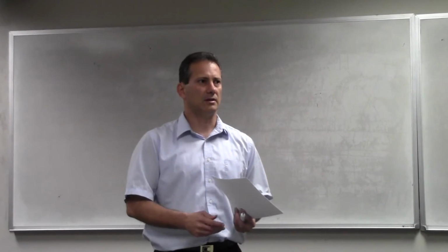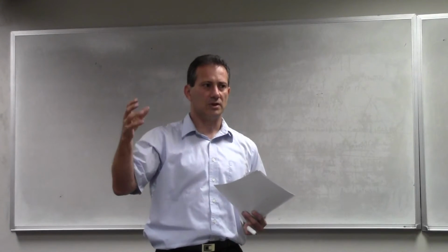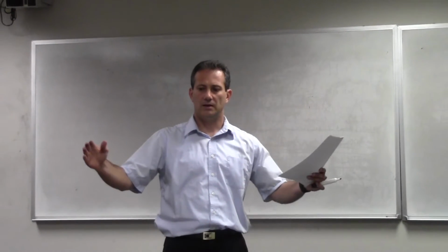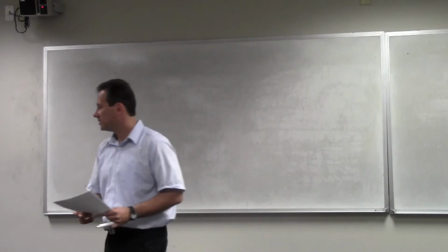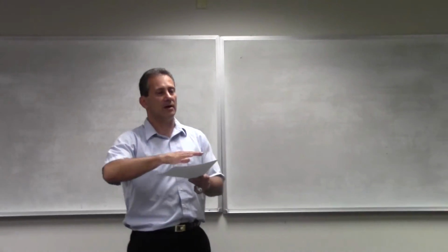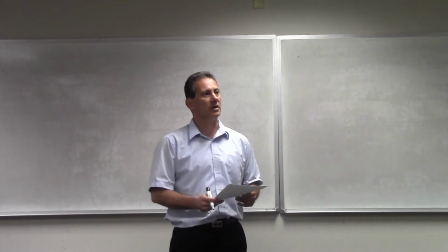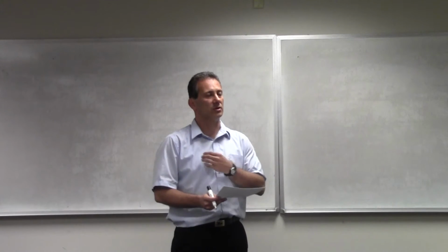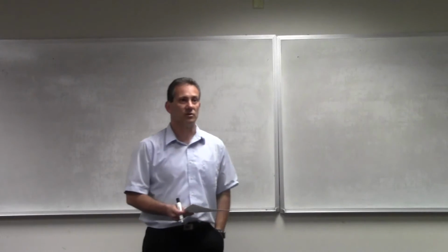With the uniform signal, you get essentially 20 log of Q, where Q is the number of quantization levels. But if your signal is non-uniform, you may end up with a penalty. Particularly bad are those signals that are focused around the origin. And we are kind of unlucky there, because the signals that we care about, let's say voice and music, spend a lot of time around zero. If you present them to the uniform quantizer, you end up having a signal to quantization noise ratio penalty. It is lower than 6 times n, where n is the number of bits that you use for the quantizer.